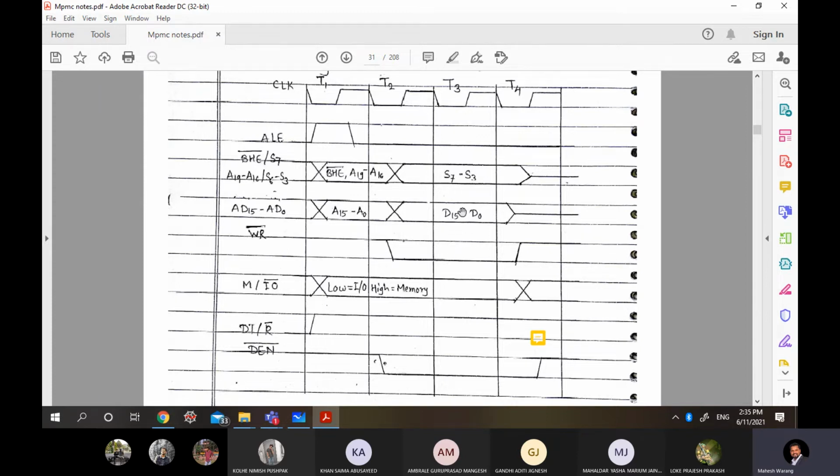And we want to write a data. So to write data, what should the write signal be below the data? The write bar should be 0. Are you getting it? Only then will it write. Okay. So keep in mind we do not make the write signal low from the starting.